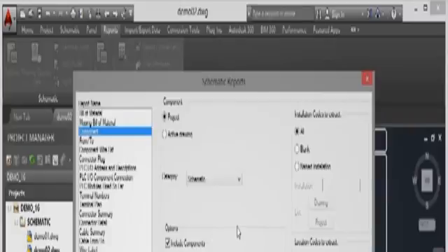Let's have a look now at changing our AutoCAD Electrical report formats. We're staying in the Demo 16 project, and I'm in the schematic subfolder. I've only got the one drawing open now, which is demo02.dwg, and it's a schematic drawing. So we'll be using the schematic panel in the reports tab on the ribbon, and we'll be using this reports icon here. So I click on reports, and let's look at changing the formats.